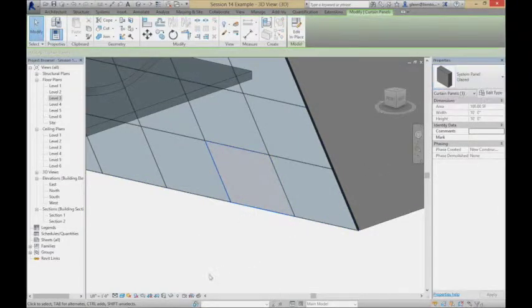It doesn't make a lot of sense to put doors in it because doors don't like to slope and all that type of stuff. So what I'll show you on Tuesday as we get started is a technique where we can carve out a little bit of the mass and actually create more of a vertical vestibule or some little entry where we can make sloping surfaces resolve with vertical surfaces and clean that up. So maybe we'll just save that for next time out of respect for your time.